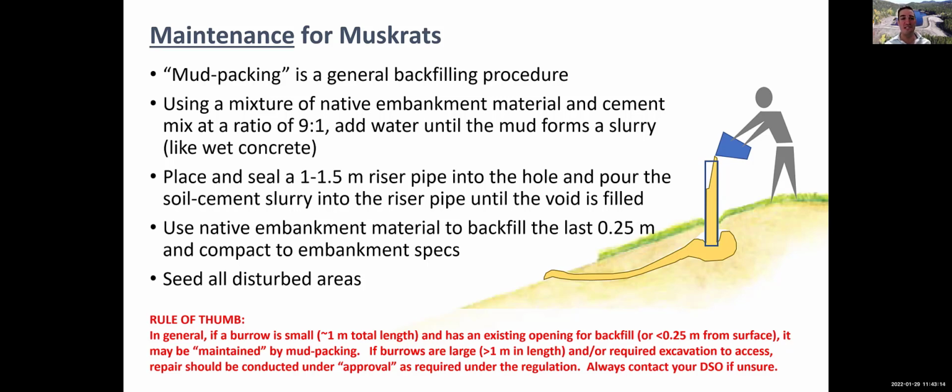So rule of thumb, if it's less than about a meter, and it can be all done with hand tools, this is kind of like weeding, removing vegetation on a small scale. You can go ahead and do that. And again, this is our opinion. And if you're ever in a gray area, you can always talk to your dam safety officer. We're going to have their contacts at the end of this webinar, and they're a great resource. You can always just call them and ask, and then you get the straight goods for your particular case.